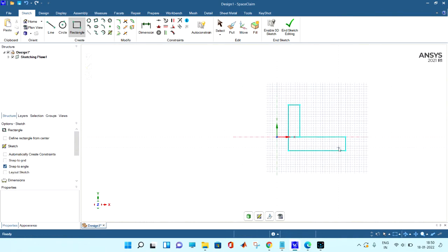So this has formed. I can revolve it, but before revolving it, I know I have to come back again, so I am just drawing the other parts also. First of all, I know the center from here. When I go with the center, I know the circle lies from here to here at 14 mm.